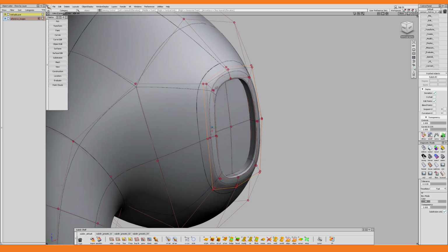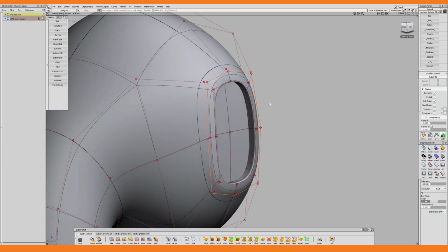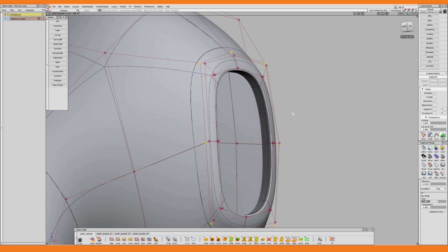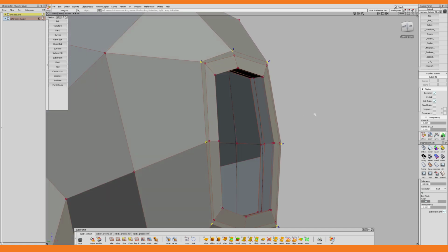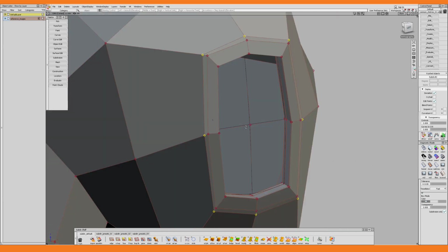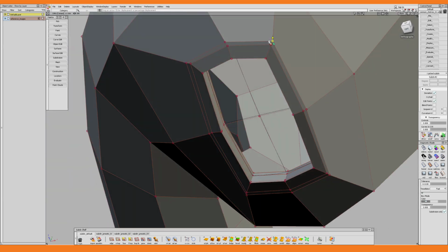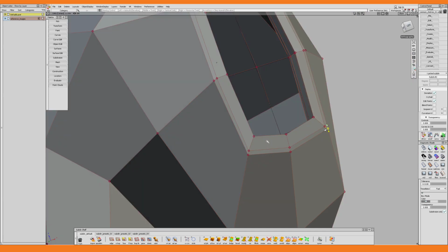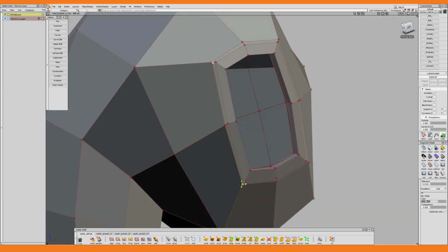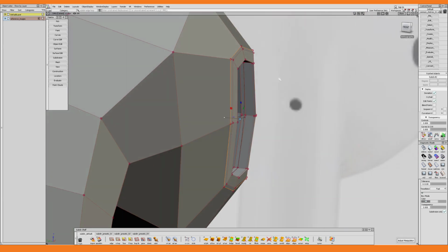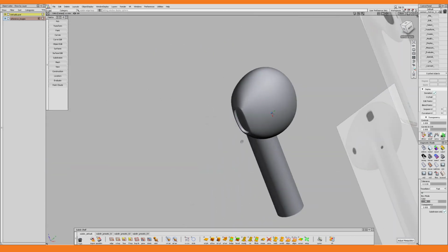To make sure that this surface isn't too flat, I would like to add some crown to it, and for that I will make use of the Transform CV Normal tool, with which I hold and drag with my left mouse button to pump the surface. Like so. With some final modifications to the vertices surrounding the hole of the speaker, I think that we can call it a day as far as the main volume of the Airpod goes, and instead move on to the bottom end cap.